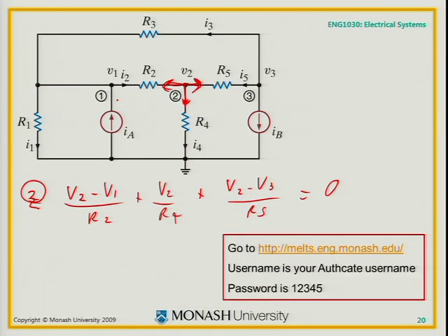I'll finish that. What if there was a voltage source here, plus minus 4 volts? So it's not between ground and a node, it's between two other nodes. There's a voltage source up there. What do I do now? Can you immediately give me an equation that relates two of the voltages in the circuit? Yep. V1 minus V3 equals 4 volts.